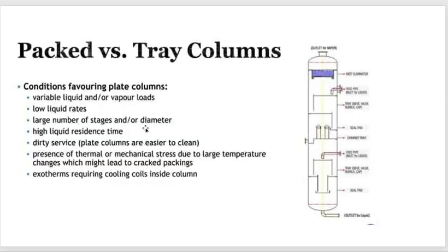Large number of stages and large diameter, choose the tray tower. High liquid residence time is required. If the residence time required is high, you have to choose a tray tower. Dirty service, because with dirty service in the packing, you will lose all the packing. Here you can shut down, and it is easy to clean.